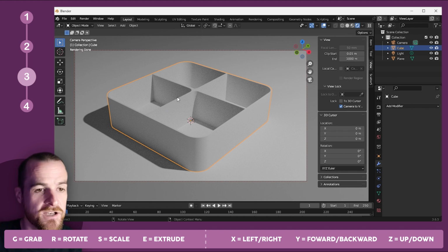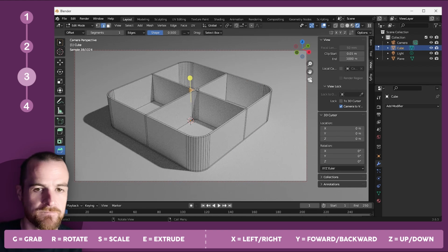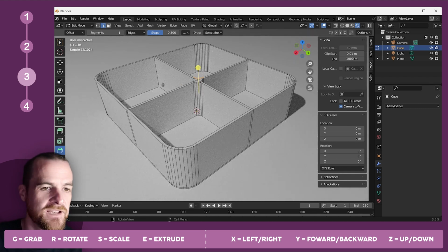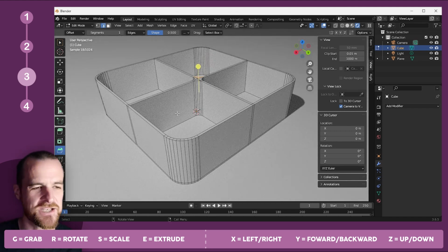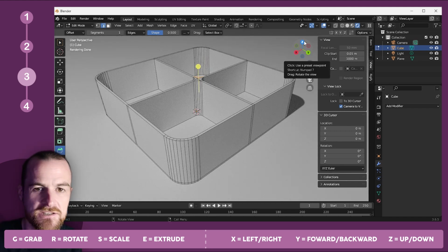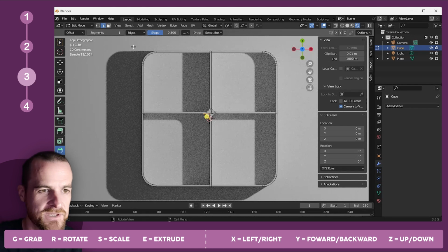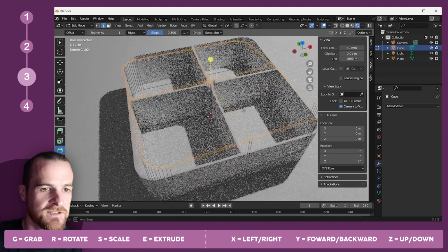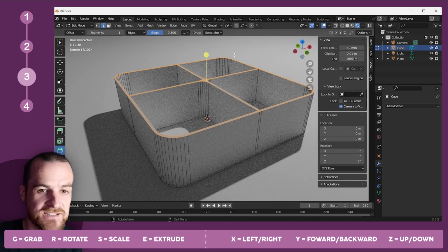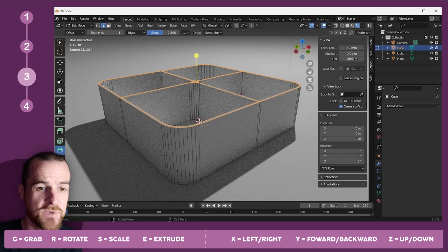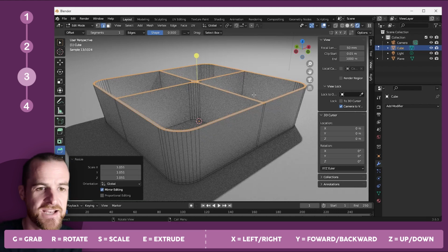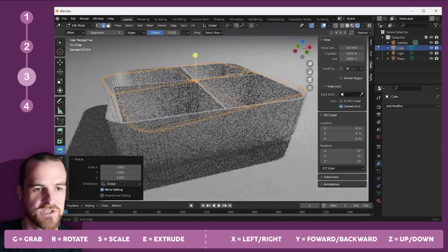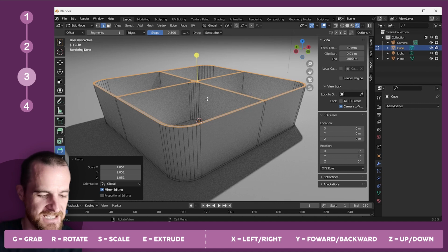Now I'm going to, selecting this, hit my tab button, and I'm just going to go outside my camera view for this. Now what I want to do is create a taper. At the moment it's perfectly vertical each way, and typically bento boxes taper that little bit. So I'm going to go to my little Z again. I'm going to select everything, and there you go. So I've selected basically the whole roof, and now all I need to do, because my origin has been set in this middle bit, it's going to make it really nice and easy to just hit the S button and create that real gentle taper to my bento box. So you can kind of see how that's getting lifted a little bit.